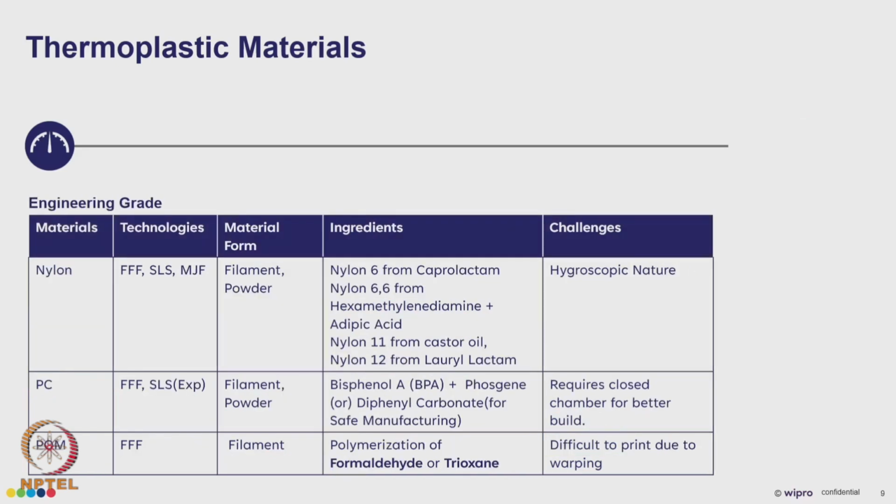Now let us get into some engineering grade materials. The first one we will see is nylon, where we could see that nylon is mostly used in FFF technology in filament form, and we have a variety of nylon categories available which exhibit different types of properties for different types of applications also.